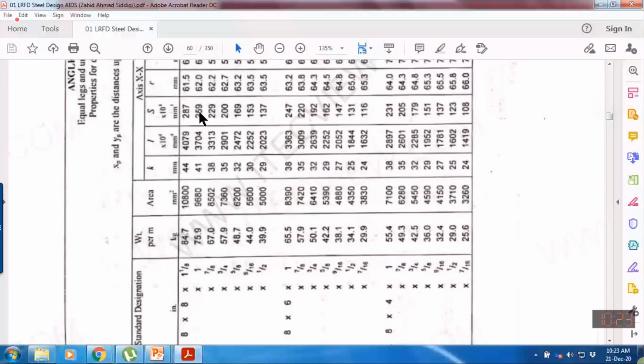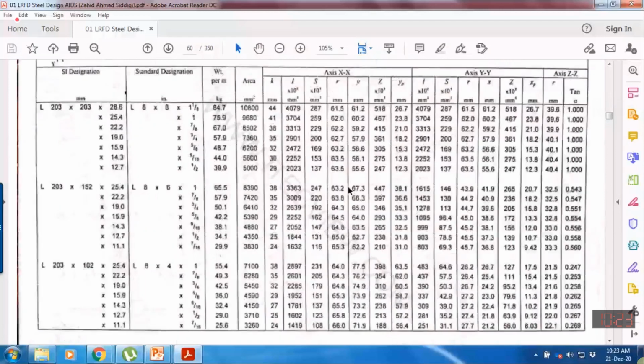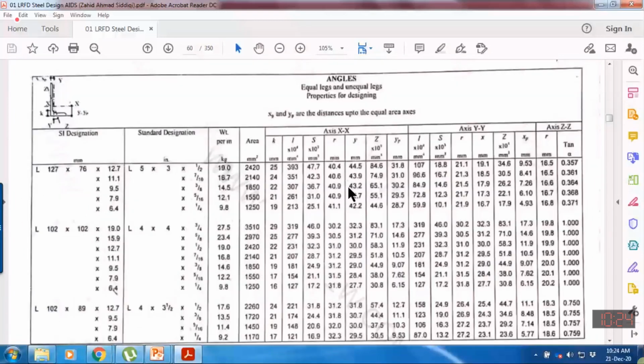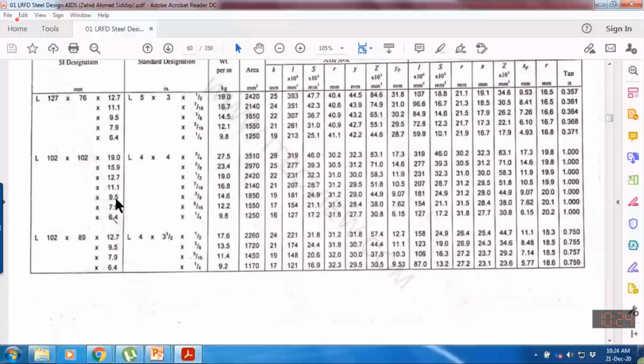29.0. Here you can also check what is the Y. This is the centroidal location along the Y axis, and we also need the radius of gyration about Y axis. So only these values may be required. So yes, we are now writing these values over here. So actually, you don't need to compute the RY actual. That is a wastage of time.